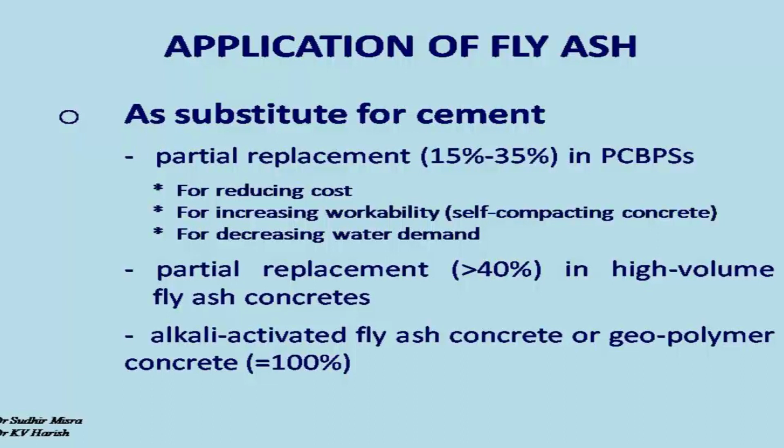So, in this type of concrete, which was initially developed sometime in the 1970s or late 1970s, and in the last 10 years has gained huge popularity, primarily because we take away completely 100% of the cement and replace it with 100% of fly ash. Now, one could immediately wonder, when greater than 40% affects the setting time and strength, will 100% not affect it?